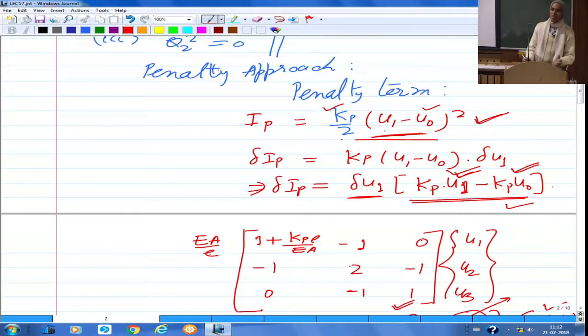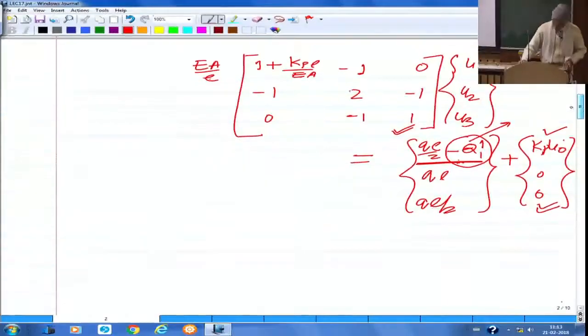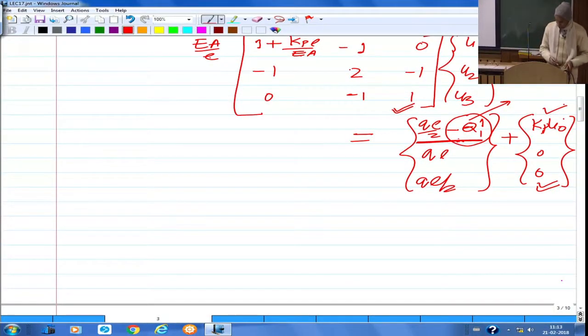the solution of the governing equations of these problems is actually equivalent to minimization of your total potential energy functional. So essentially you have a total potential energy functional for these problems, and you are minimizing that subject to the boundary conditions. Those boundary conditions can be implemented as a direct substitution, penalty, or even Lagrange multiplier approach. For more details you can read from the book, and then you can actually implement this in your lab classes.